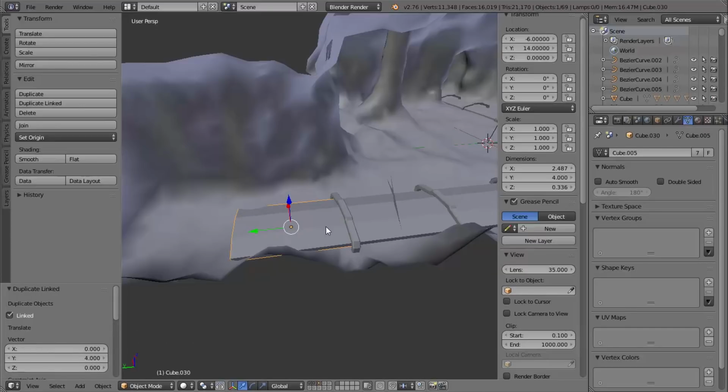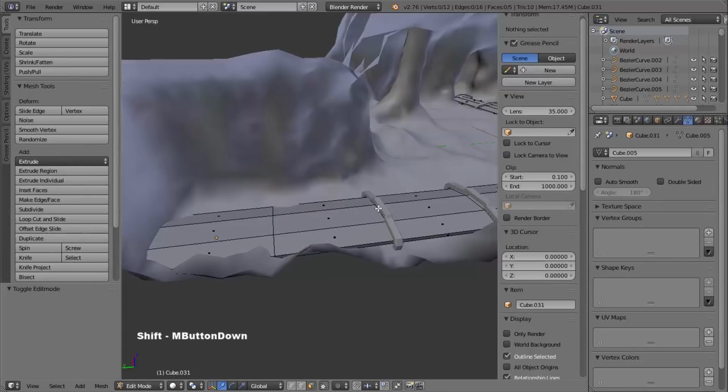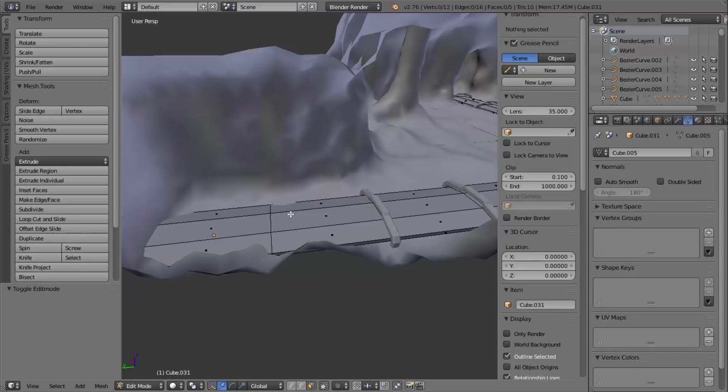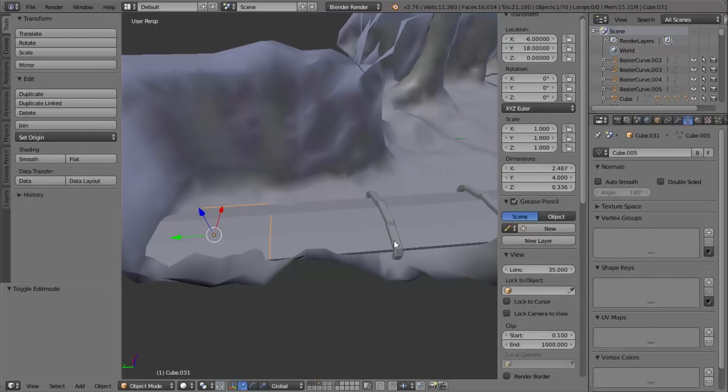And as before, I can press Shift and R, and that will duplicate the previous operation. And to show you what I meant about the linked objects, if I go into edit mode for this, you can see that all of the conveyor sections are also going into edit mode as well, showing that they're still linked. Okay, so going back to object mode, what I want to do is duplicate this rail object in the